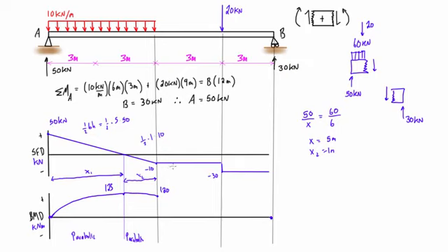Now these next two sections have horizontal lines in the shear force diagram, so that's going to just give us linear changes in magnitude here, so basically just sloped lines. When we look at this area in here, it's just a rectangle, so it's base times height. Its base is 3 meters, times its height of 10, so this will be a change in magnitude of 30 across this distance, and it's on the negative side, so that change is pushing us towards the negative direction. So 120 minus 30 is going to bring us down to 90, just like that, and then you will just connect this with a straight line, boom, like that.